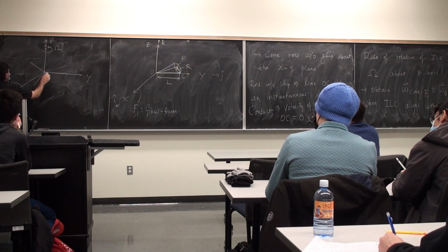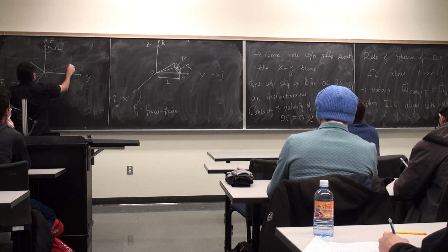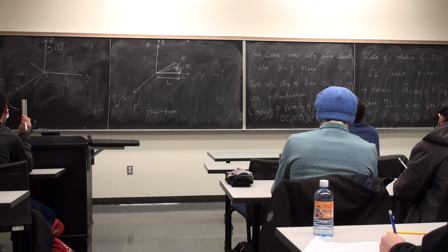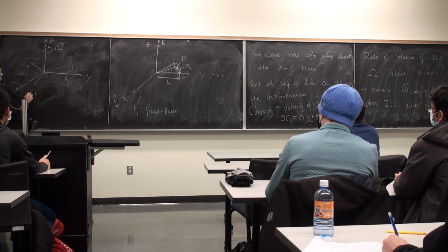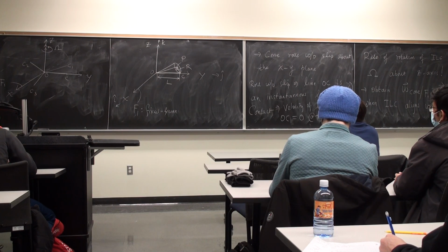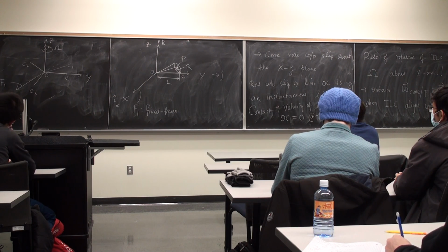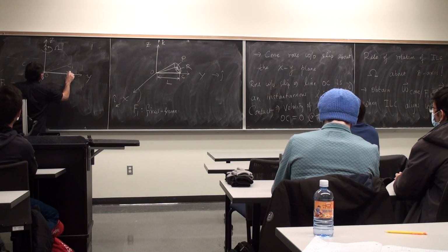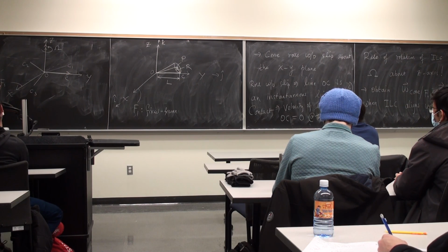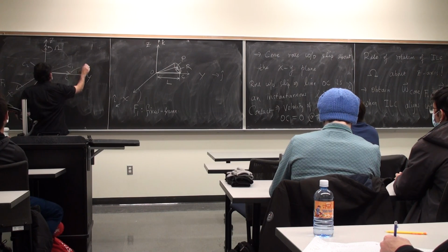Right, so this is the line OC. At the next instant in time, this is some line OC1 because the next point is coming in contact. At some other instant in time, OC2, OC3, and so on. And so if I attach a coordinate frame to this line OC, what are the potential directions that I could choose? I could choose a unit vector along the line of contact. I could call that a direction E2 or something.